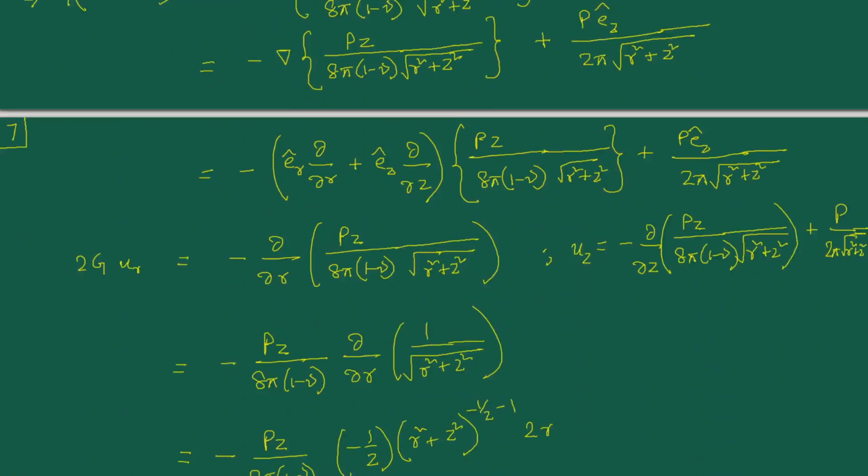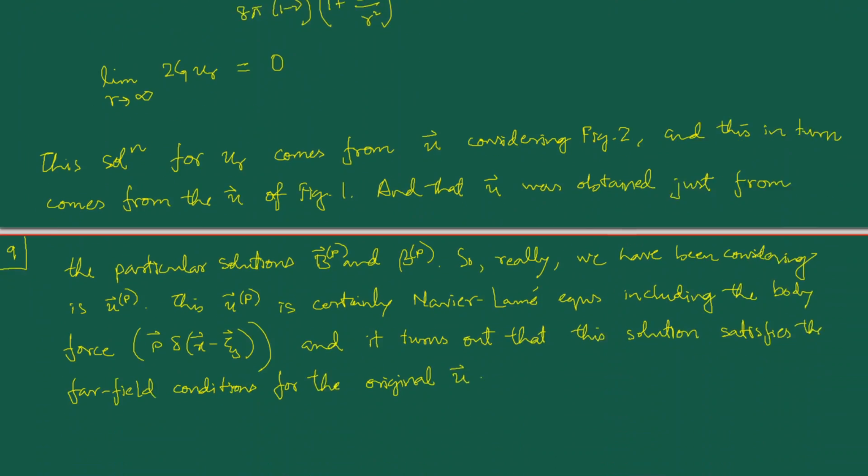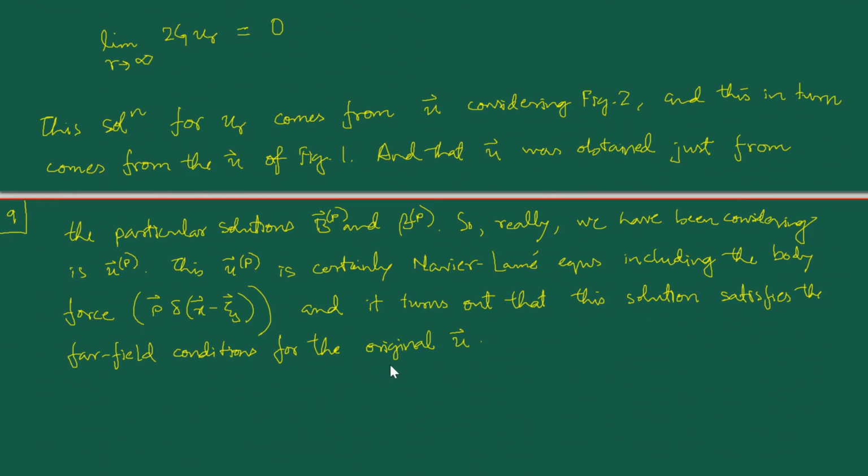Okay, so with this explanation, the solution part for the Kelvin's problem as far as the displacements is concerned is done. Now what we can go on to do is, from these displacement fields, find out the strains, and from those strains we can find out the stresses. And once you find out the stresses, you can do some verifications. Those are the kind of verifications which have been carried out in our textbook example. So we can do those things very easily now.